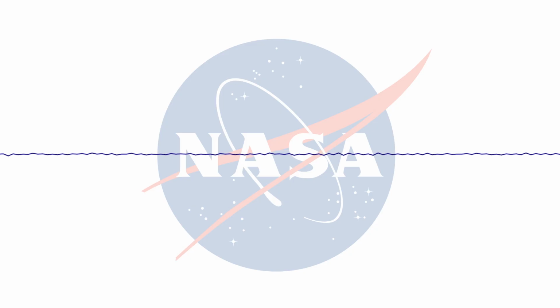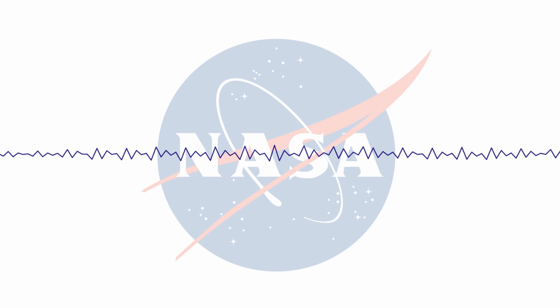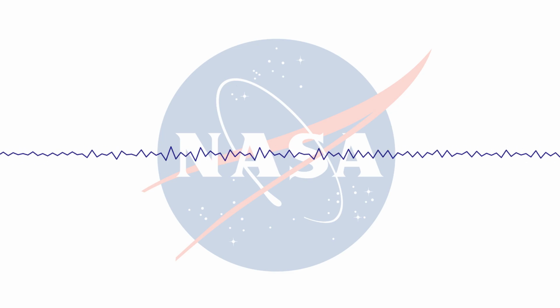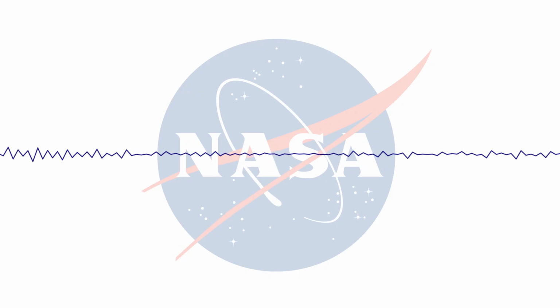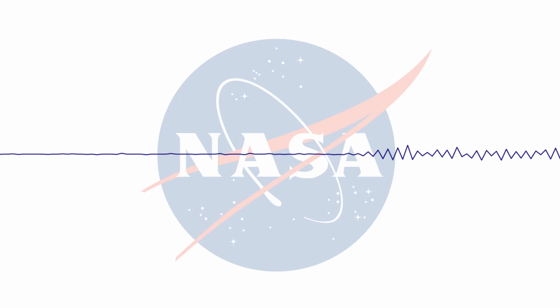Perhaps you stated it. What is the accuracy of the altimeter? The least count of the altimeter is 1 meter. The accuracy is dependent pretty much upon the slope in the area which is illuminated and a little bit on the albedo in the area which is illuminated. In general, I think it's fair to say that the reading that we get from the altimeter will be correct to within 3 to 5 meters.